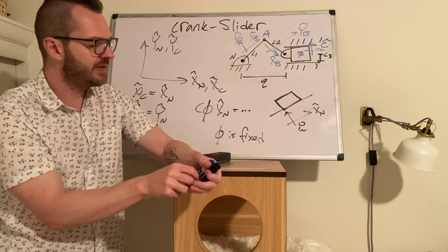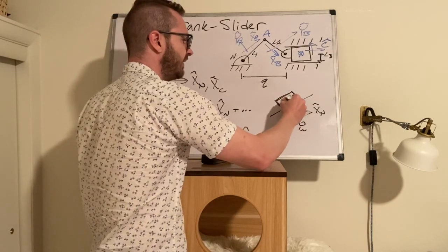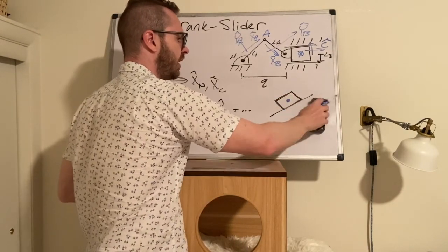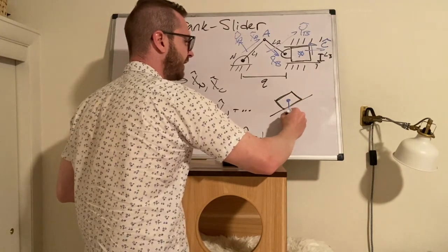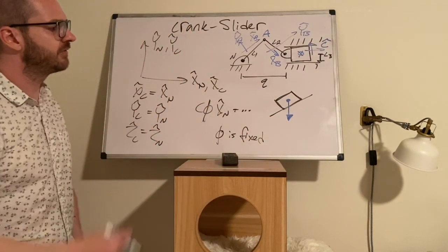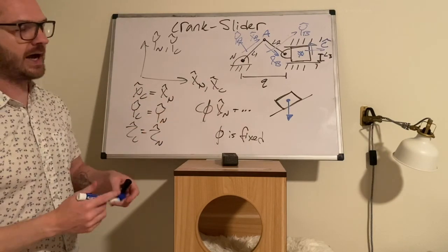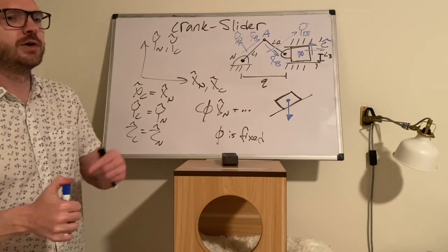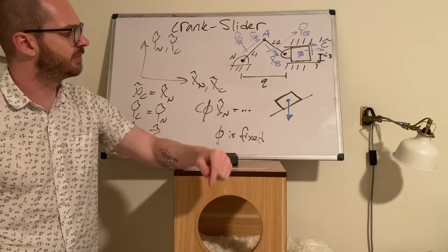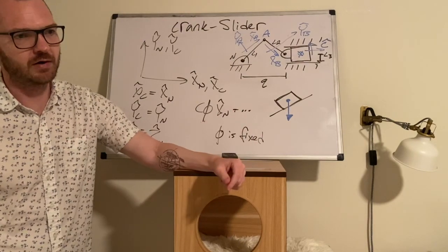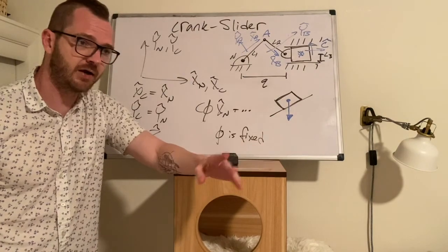But also beyond that, consider, what if we start talking about the weight of this block? There's gravity acting on it, and gravity is going to act that way regardless of how you have chosen to rotate your inertial frame. So even if you rotated the inertial frame, we still have to have some other frame talking about how gravity is acting on this. So good practice: just leave the inertial frame as it is, up, down, left, and right.